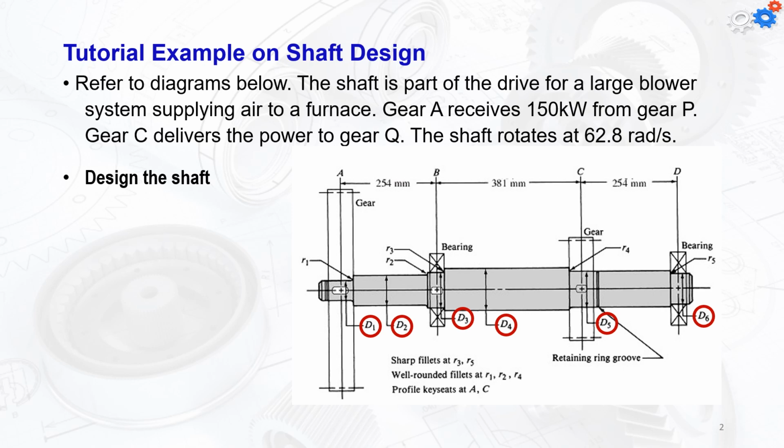I can simply use the same diameter shaft. I mean, it's going to start the same diameter from the beginning till the end, which is going to be the maximum value again to have for the diameters according to the maximum force we're going to have for this section. But the thing is, we need to reduce the size of different sections to reduce the weight of the shaft in general, because I don't want the weight of the shaft to be problematic for the total design for the machinery we are going to make.